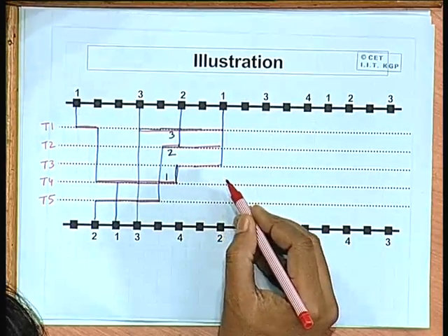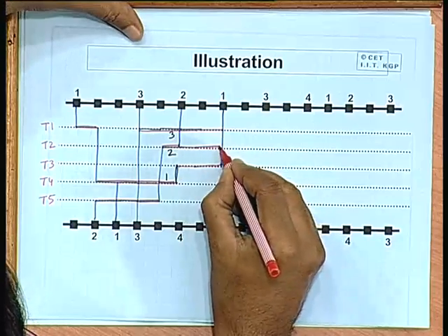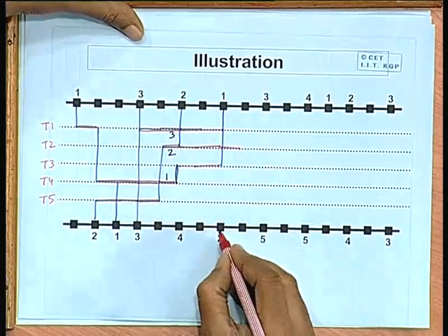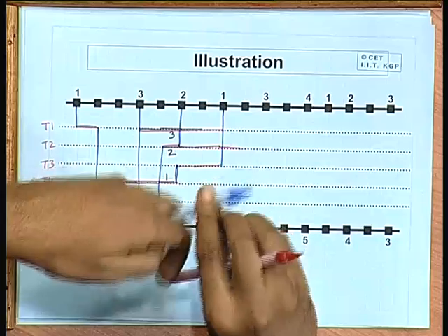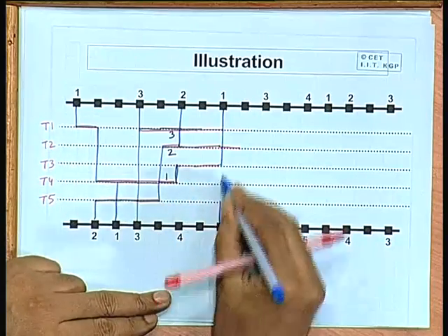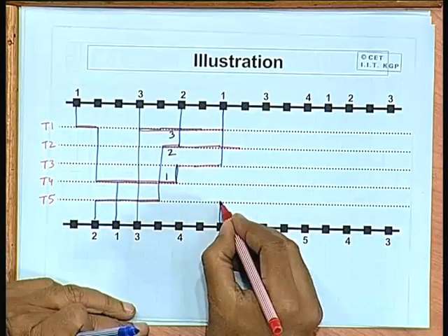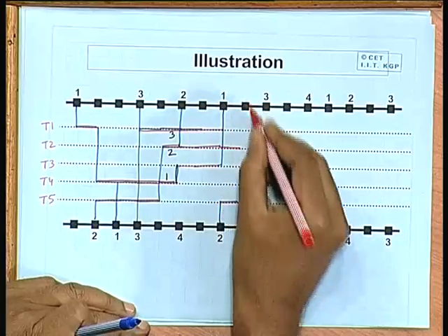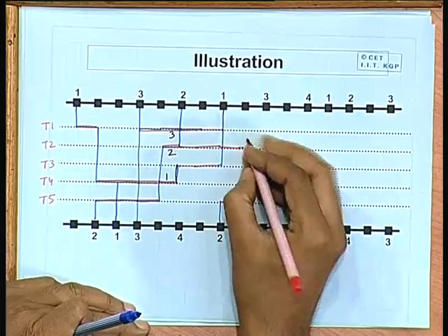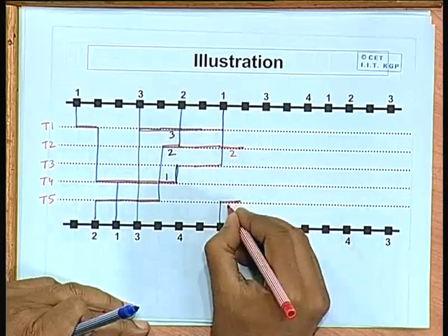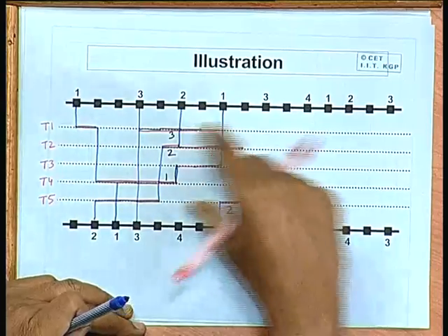So, this net 2 will have to be extended further on the right, and this net also, which was supposed to be connected, you cannot connect here, you also extend it to the right. So, now in the next column position there are 2 split segments of the same nets which are proceeding.